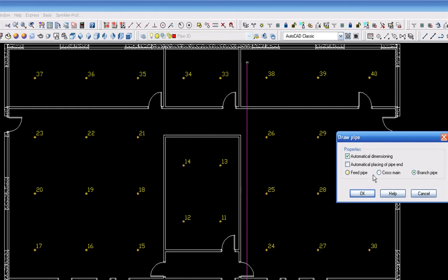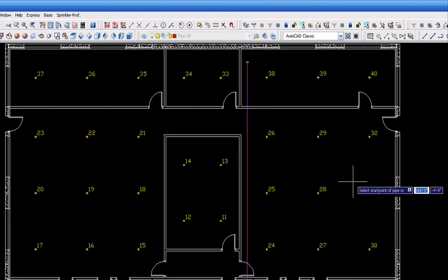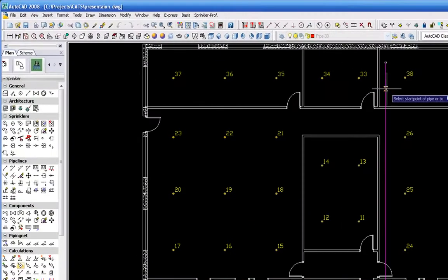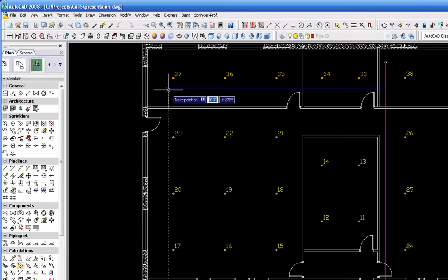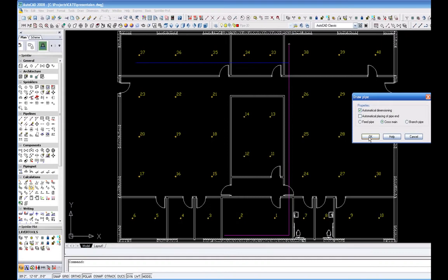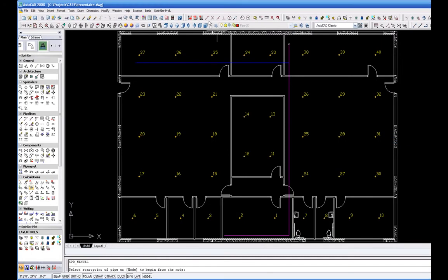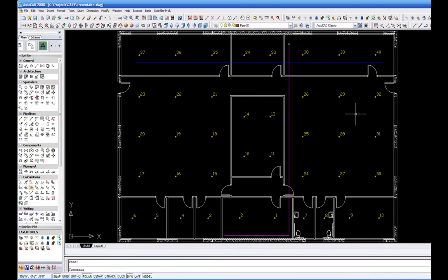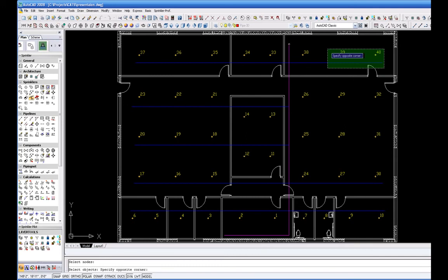You are now ready to select the location on the fire sprinkler main line where you would like to place the branch pipes supplying the fire sprinkler's heads. Using the Snap Nearest command in the CATS Commander, you can draw the branch pipe center line alongside of or above the fire sprinkler heads. After the layout is completed, you connect the sprinkler heads automatically to the pipes by highlighting those sprinklers that are going to be connected.